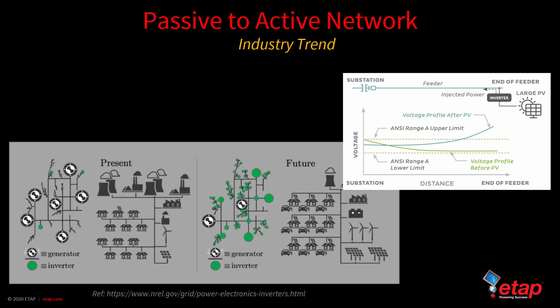In the fall of 2017, for example, California became the first US state to require the use of advanced or smart inverters to essentially take care of this problem. These changes were implemented through updates to Rule 21 and require inverters to have certain capabilities to ensure proper operation of the electric grid as more and more renewables are connected. Phase 1 went into effect in September 2017 and requires that any solar project which applies for interconnection to the grid must use an advanced inverter capable of performing 7 autonomous grid support functions.